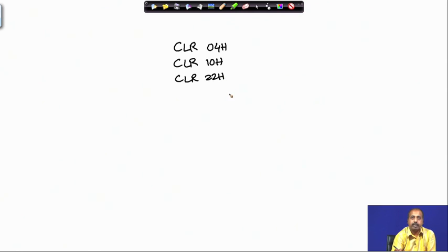Now, we will check the individual bits, the carry, auxiliary carry and parity, and accordingly set the bits. For the carry part we can write like this: JNB PSW.7, L1. If this bit is not set, PSW.7 corresponds to the carry bit. If you look into the bit addressable memory, PSW.7 is the carry bit.